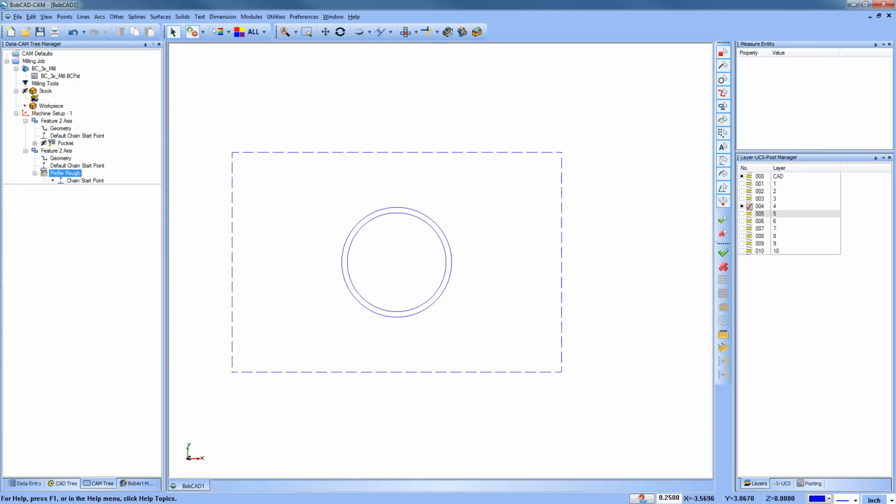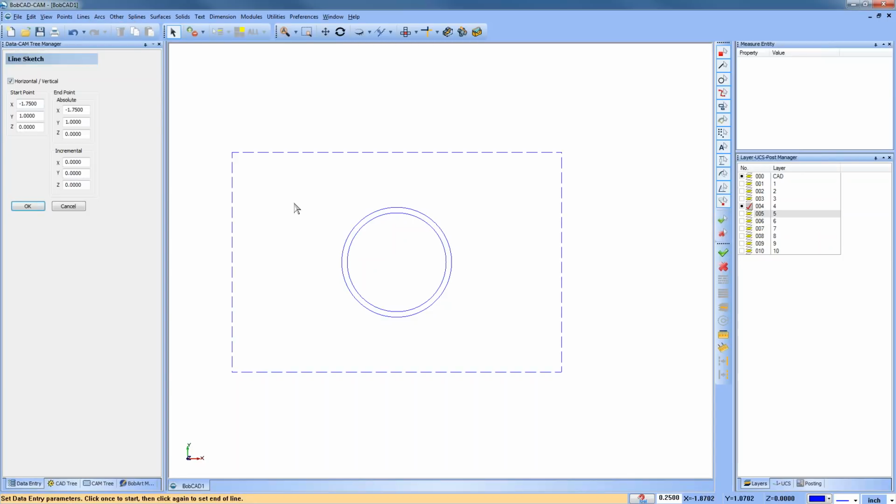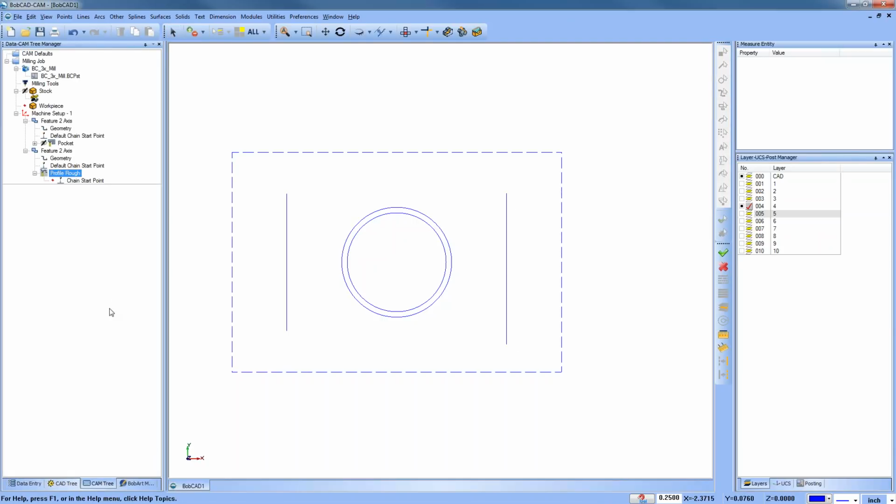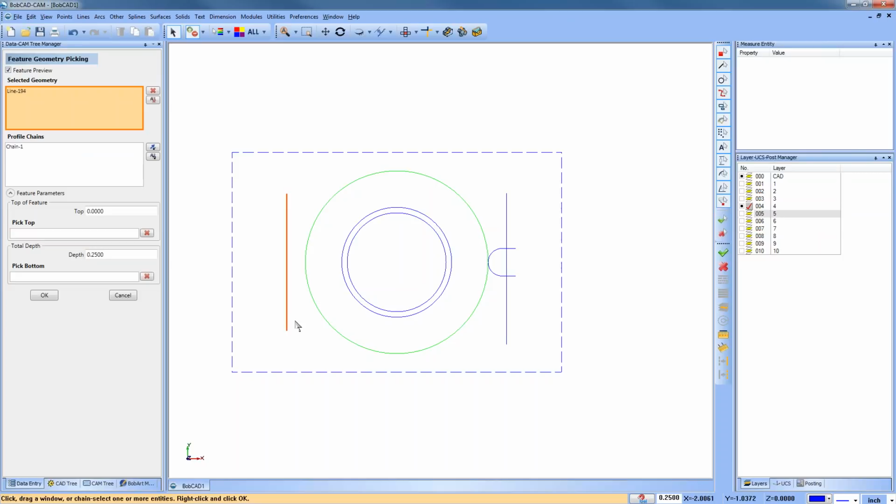The other thing I want to do here is just sketch some lines. The next one that I want to talk about is actually called contour ramping, and there are a lot of different ways that you can use contour ramping. Let's remove this geometry. Let's reselect this line and this line. Then instead of jumping ahead, I'm just going to look at the directions that I have them going. I'm going to set this one this way and that one that way.